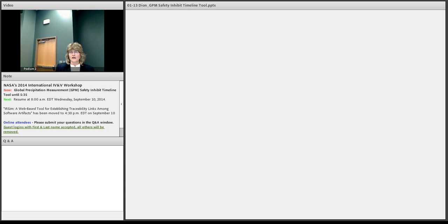Okay? And I made a comment to the person who wrote the procedure, and she came back to me and said, Shirley, this is a solar array test. Why do we have to worry about the high gain antenna arming plug being removed? So then I realized at that point that the systems folks hadn't told the INT folks, or at least not the person writing the procedure, that those 2 inhibits were coupled together.